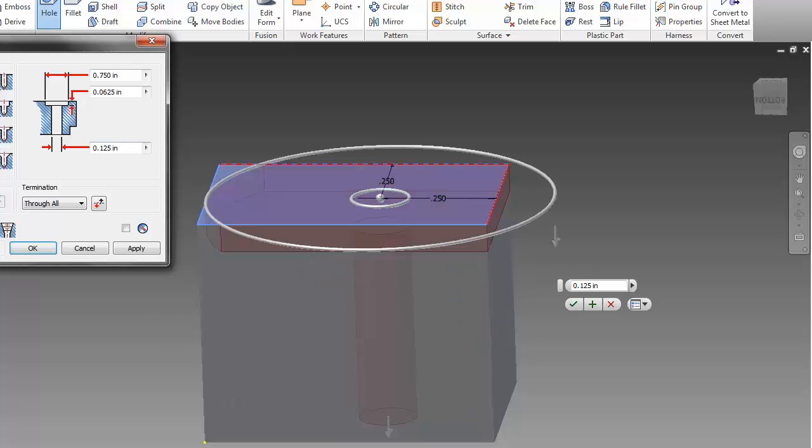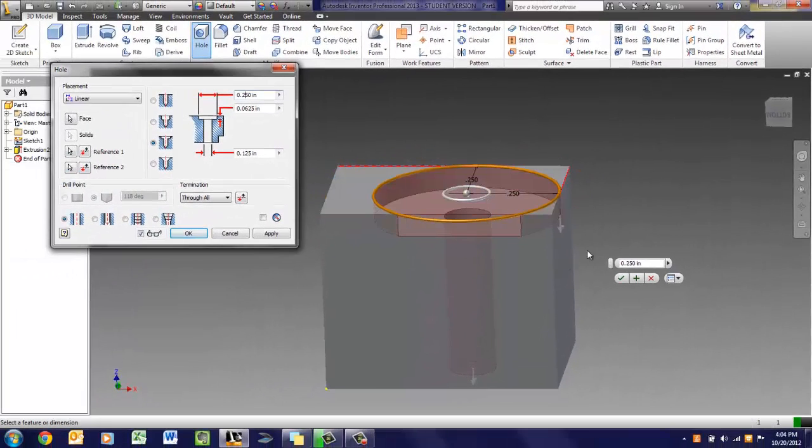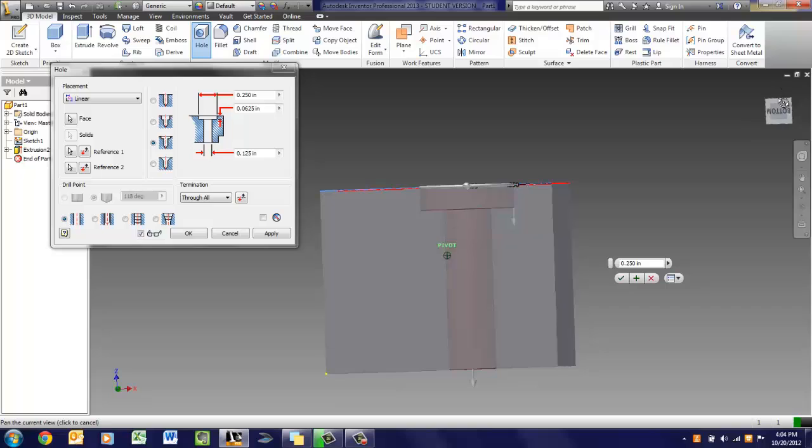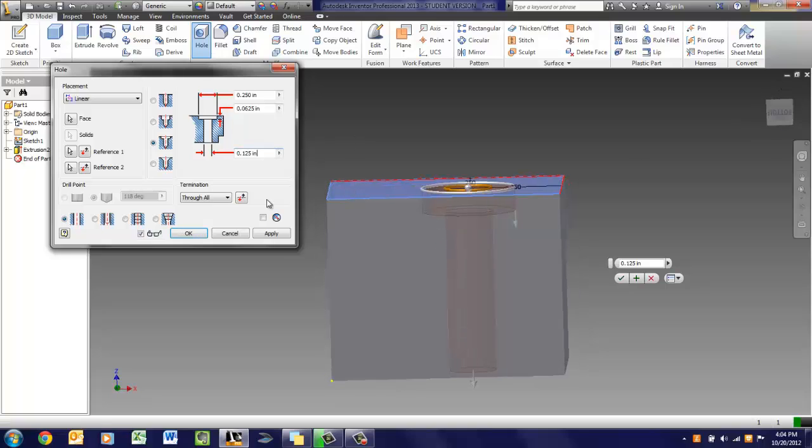We also have spot face, which is going to be much smaller, and again, we would want it to be 0.75 or 2.25. We could adjust that down. Okay, that's going to make it a little smaller. You can also give that a depth and dimension here. The spot face would be for something more like a screw head.